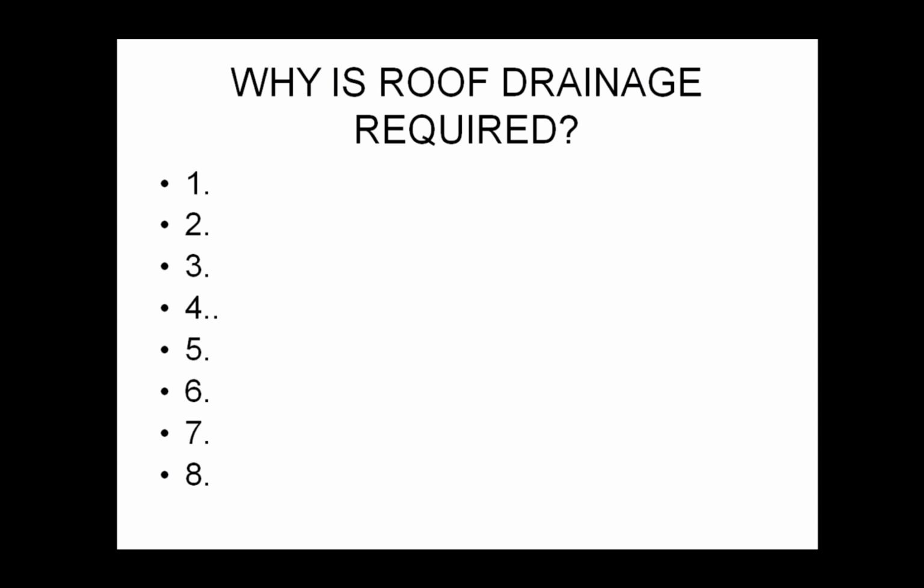What's the problem with that? Yeah, of course, weight. And then now you have to somehow still provide for roof drainage. And why is roof drainage required? Basically you don't want the buildup of water or snow up on the roof, adding weight to your roof. If it's cold, it could then freeze and expand and contract and damage the elements of your flashing and your roof and your drainage. So roofs need to have drainage to accommodate this water to prevent cave-ins of roofs.